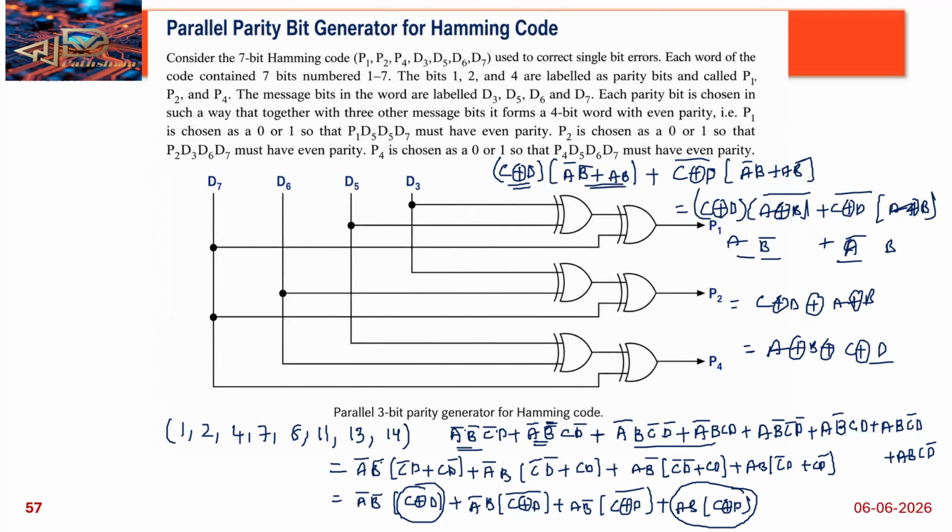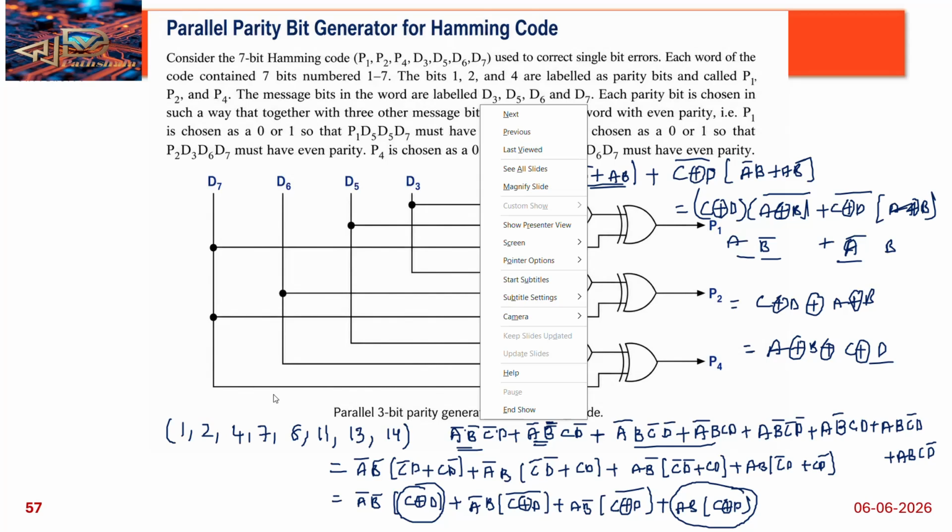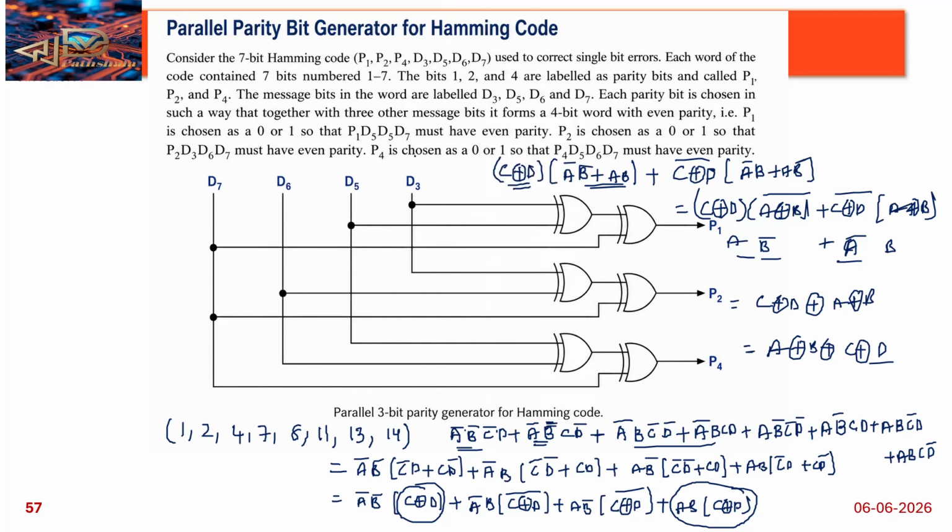So how the Hamming code is performing here means same like that, but depends upon the data. Suppose the data bits, 4 data bits they have given, like D3, D5, D6 and D7. So this is a 4-bit message I am giving. Any bits, either 1011, 4-bit.